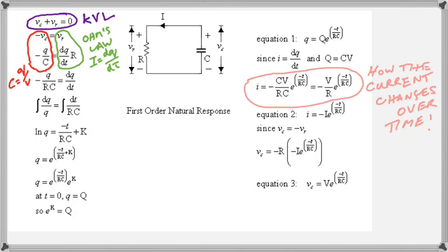In this one, we have small i, and we have a term V upon R. The R is fixed. The V is also fixed because the big V was the initial voltage that was across the capacitor before it started to discharge. And the exponential term, e raised to the power of minus t over RC, is the decay factor that reduces that quantity V upon R gradually to 0. So by plugging t in there, we can find the I at any point in time.